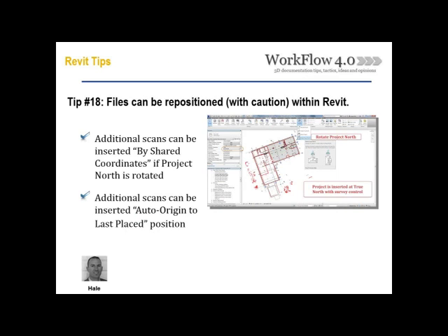Tip number 18, files can be repositioned, and within parentheses, with caution within Revit. I know in previous presentations that I've watched and I've presented in before, the general rule is to never move the scan data within Revit. However, there are going to be times on projects where, let's say, the project is already modeled and you're coming in and doing a 3D laser scan to verify things that have already been modeled.